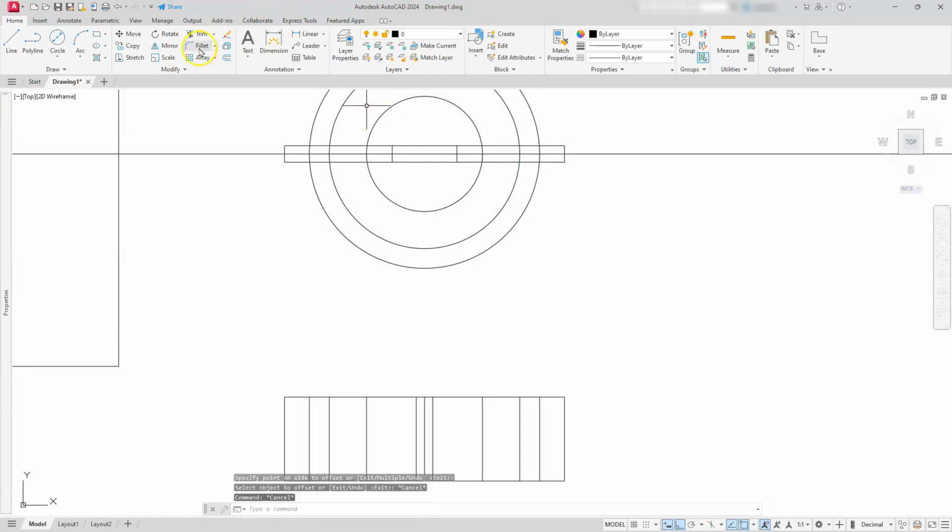Let's go back to the trim command. And this time, just leaving it at the quick option, I can trim off these portions here. I'm going to also trim off these portions in between, and you can see I accidentally trimmed off something I didn't need. So I just go to the undo function in the command, and then go back and trim off these portions, right? Just going to go ahead and use a fence and make it a little quicker on myself here.